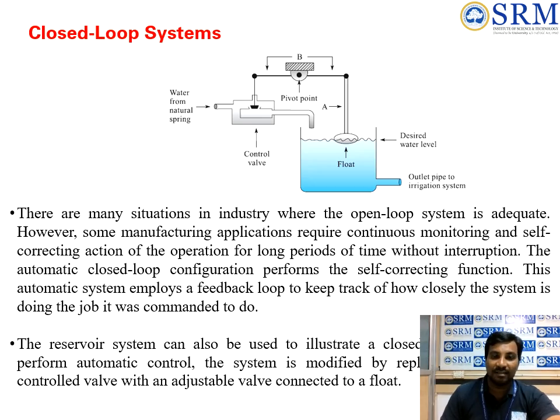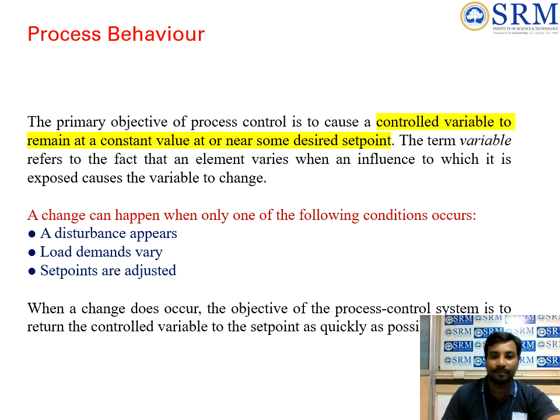As the water level rises, the float moves upward, pushing the lever and closing the valve, thus reducing the water flow into the tank. If the water level lowers, the float moves downward, pulling the lever and opening the valve, thus allowing more water into the tank. To adjust the desired level of water in the tank, the float is moved upward or downward. This is an automated process, or closed loop control. These systems have a self-regulation capability and are designed to produce continuous balance.